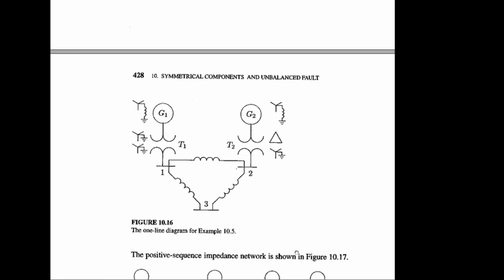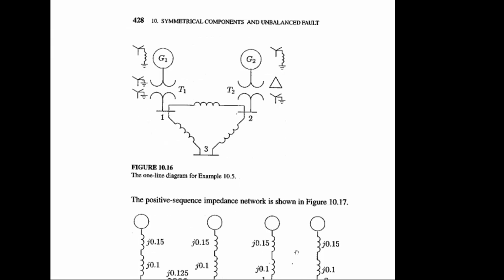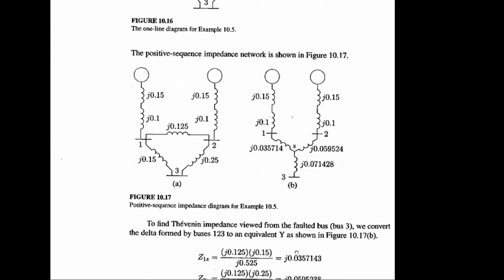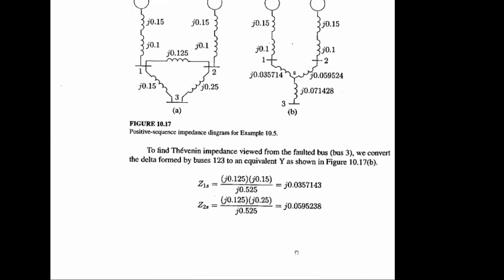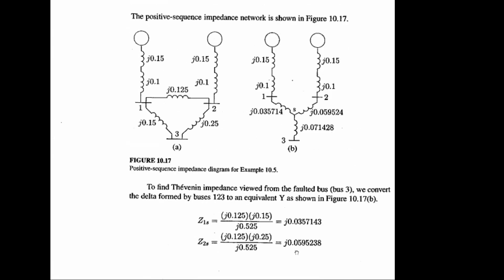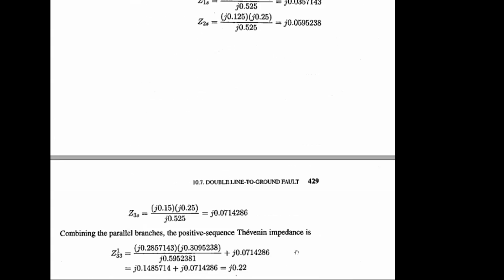Okay. So when you have all the sequence impedances Z0, Z1, Z2 in your hand, you have to use those three sequence impedances for fault current IA determination based on different scenarios, like single line to ground fault, double line to ground fault, line to line fault, and three-phase fault. These four cases are possible if you have generated the impedance information correctly, Z0, Z1, and Z2.